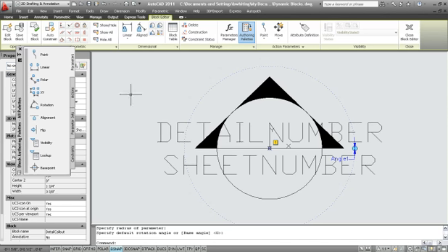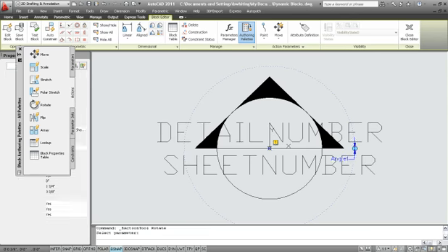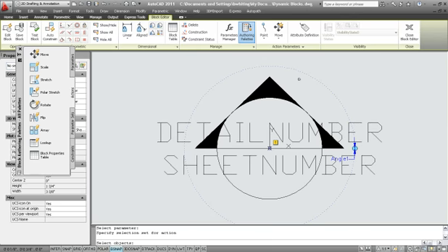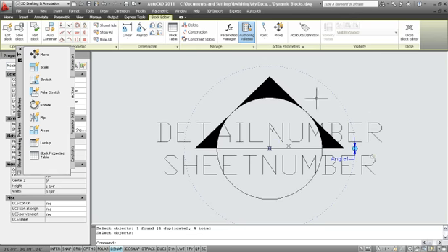So now that I have my parameter in, I need to apply an action to that. I've got rotate parameter, come to actions, and I'm going to perform a rotate action. So I highlight that. It asks you which parameter. So I'm going to click on the parameter that I just created. It asks which objects I want to rotate, and I'm going to select all the pieces that I want to rotate, which is everything outside of the center, so not selecting this horizontal line or the two attributes. So I've selected those, I hit enter, and now I have a rotation action applied to this block.